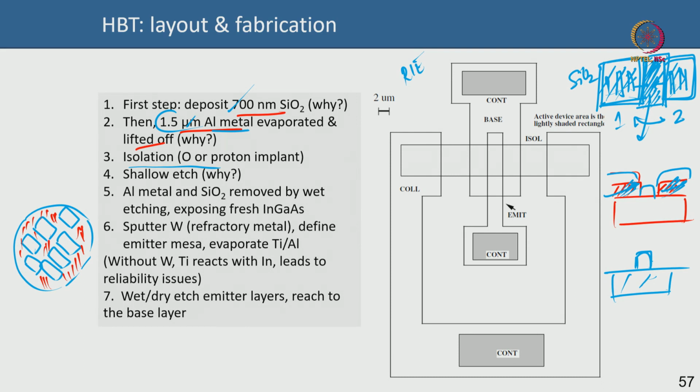Now after you define the active area, and this is the top InGaAs, for instance, first you will put the emitter. Okay, then you will do the base, then you will do the collector. That's the sequence in which you fabricate compound semiconductor HBTs, and that's different from the sequence in which you fabricate silicon BJT, where you first do the base, collector, of course, and then you have the emitter at the last. So the emitter process comes at the last in silicon BJT, and you do not want to play much around with the emitter process because it is the last in silicon BJT.